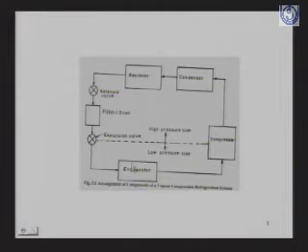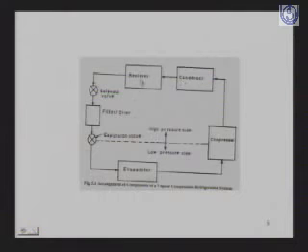During the evaporation, they take the heat from the system, that part becomes colder, and the vapors move further. So this cycle, from compressor to condenser and then to the expansion device and then to the evaporator, keeps on going.